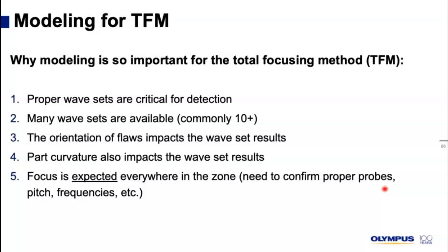Then, focus in TFM is also expected to be everywhere in the zone that the user created. So we really need to confirm that the proper probe, the proper pitch, the frequency, all of this, how it affects our signal, and if it is proper for the inspection that we're trying to do.